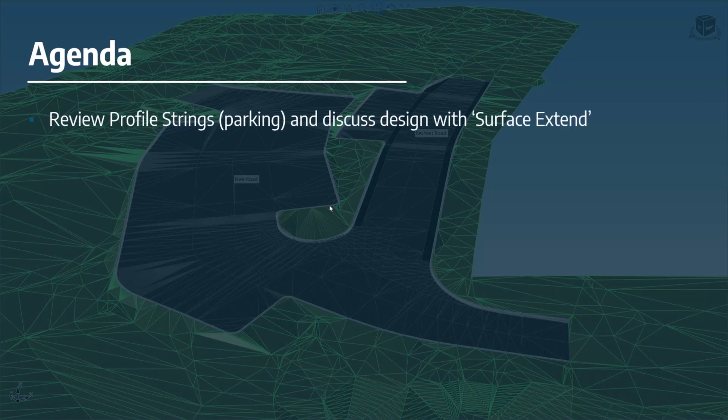So first thing, we will have a look at the profile strings that we have pre-created for the purposes of the parking bays, so you guys can see how we've assigned the elevations to them, because there's a very, very good tool called Surface Extend which will basically help us assign the elevations and make sure we get this nice tie-in. Model Builder is not about setting elevations of strings and making sure you've got those tie-ins. It's about simply getting the geometry of your strings to fit together.